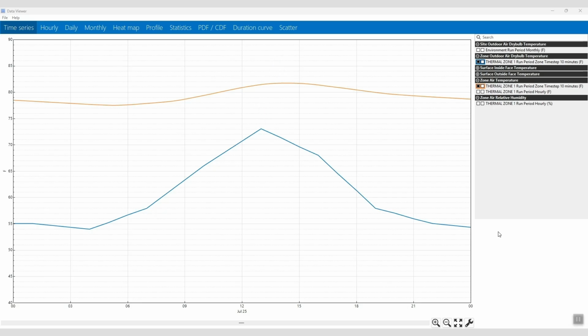Second, the indoor temperature curve is much smoother. The building's materials are damping those sharp outdoor swings thanks to their thermal capacitance. Third, you'll notice indoor temperatures staying higher than outdoor. That's solar radiation pouring in through the south-facing windows, warming up the space. And fourth, well, let's be honest, this building would be pretty uncomfortable to spend time in without any HVAC.